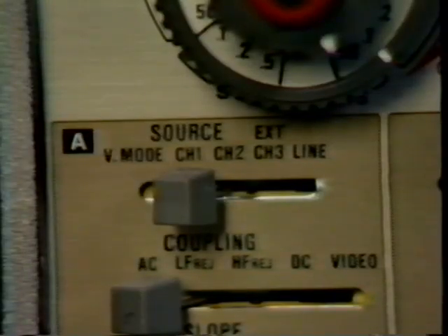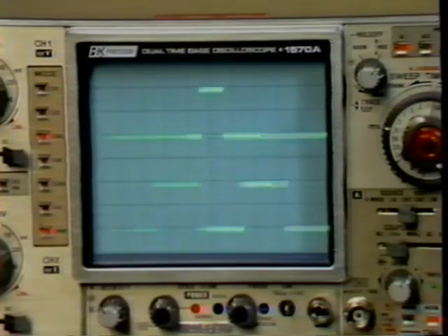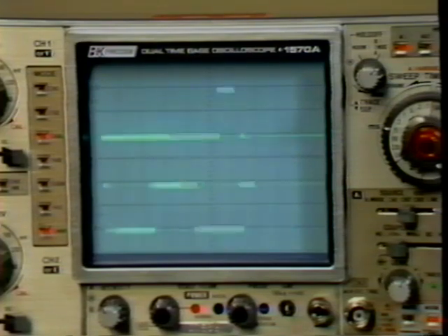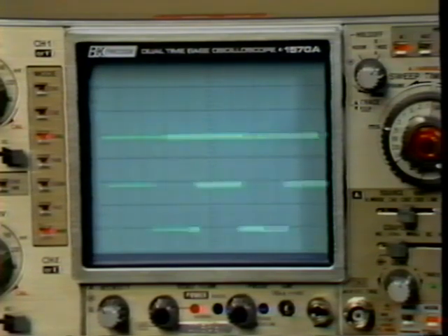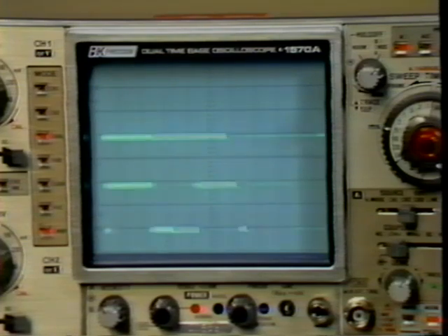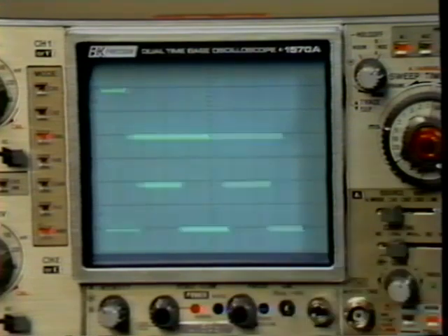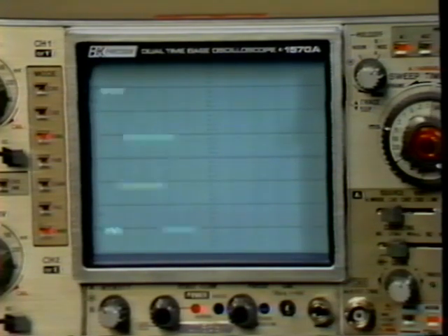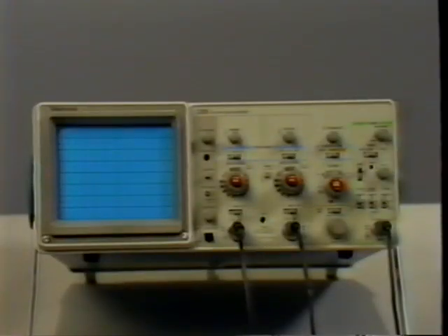When displaying two channels at once, we must also decide which channel to use as our sync source. If the two signals have different frequencies, always sync on the slower one to produce the clearest possible display. If we use the faster signal for sync, sweeps will begin at widely varying points on the slower signal, and there will be no possibility of a stable display. If the slower signal provides the sync, there may be some instability in the faster signal, but the display will be much clearer. A complication arises when the two signals are not related.